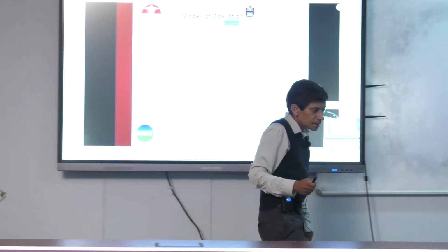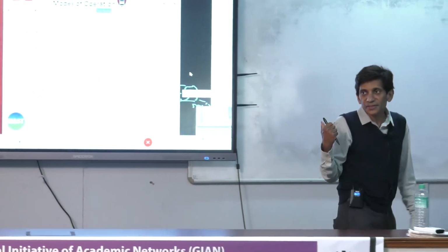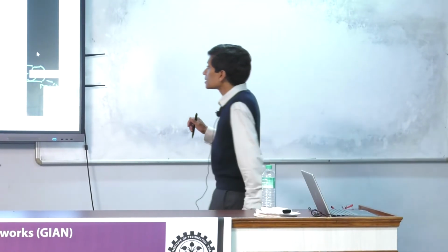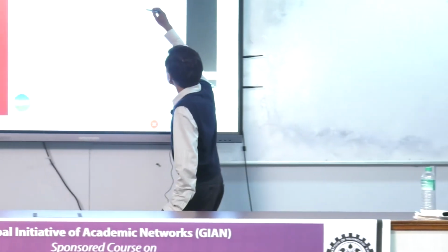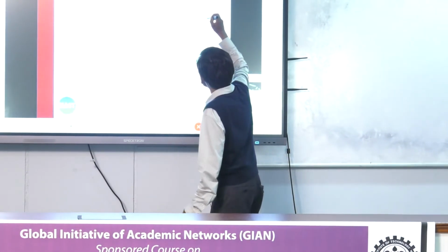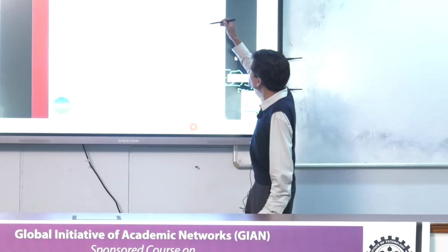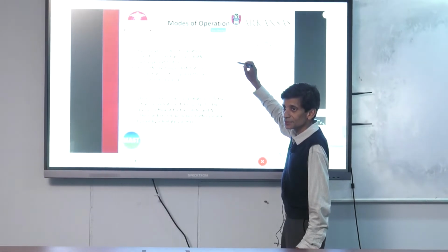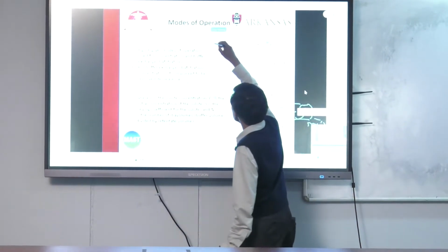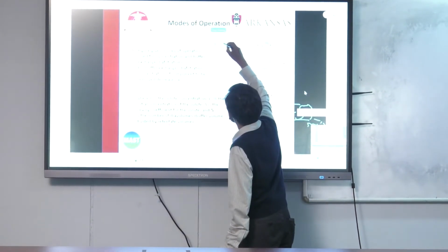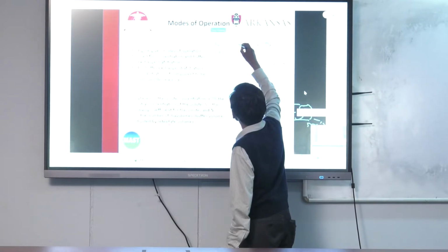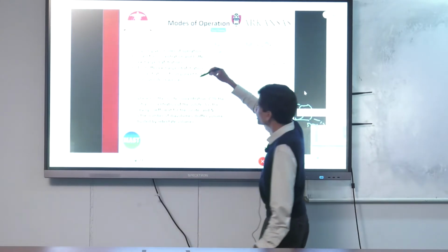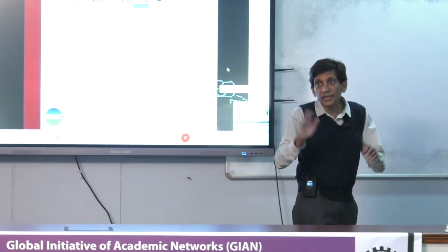By the way, that's very easy to derive. So if anyone's interested in deriving it, we can do that sometime. It's very simple. It's just a mass balance on your recycle tank. You say in minus out equals accumulation. There's nothing coming in, but you're losing your component going out. So you can then just say dC/dt multiplied by V equals in, which is 0, minus what goes out, which is your permeate flow rate multiplied by concentration, and you can integrate that and end up with this. And if you like, we can work that out later.